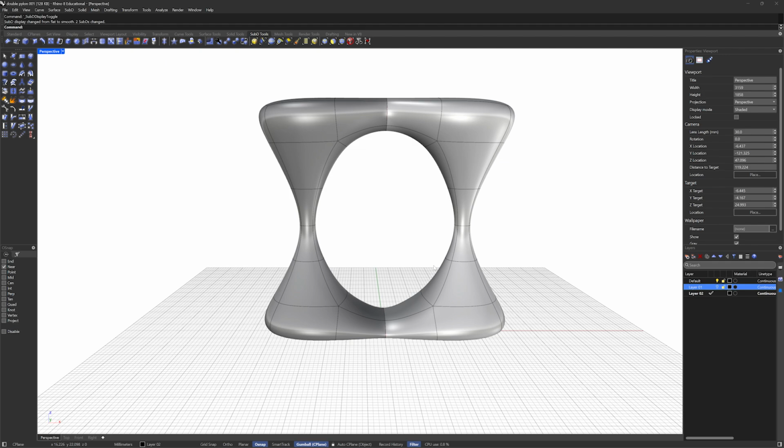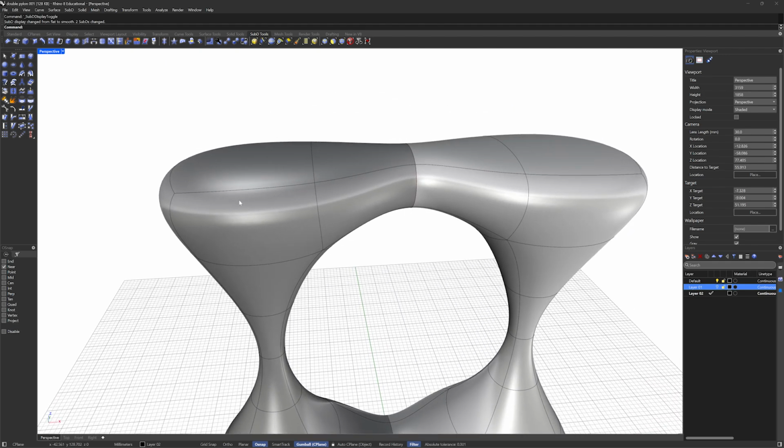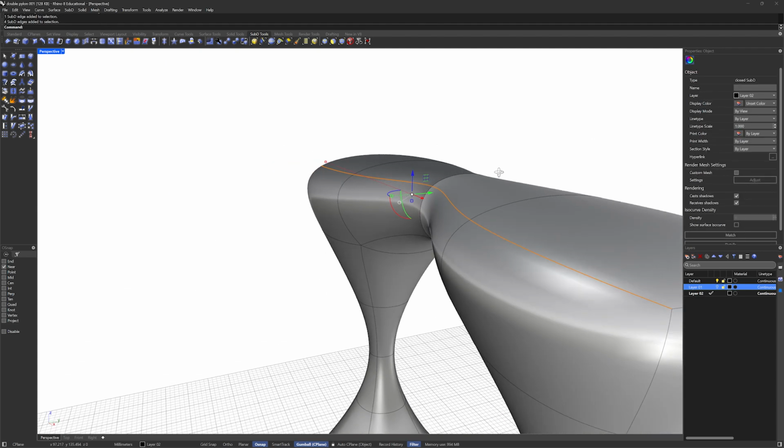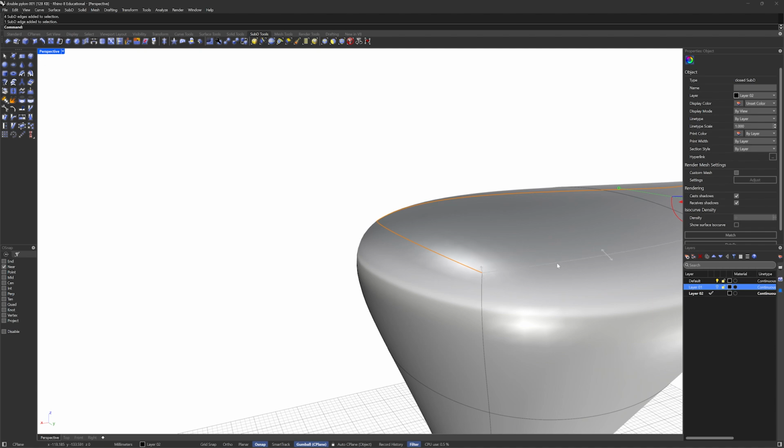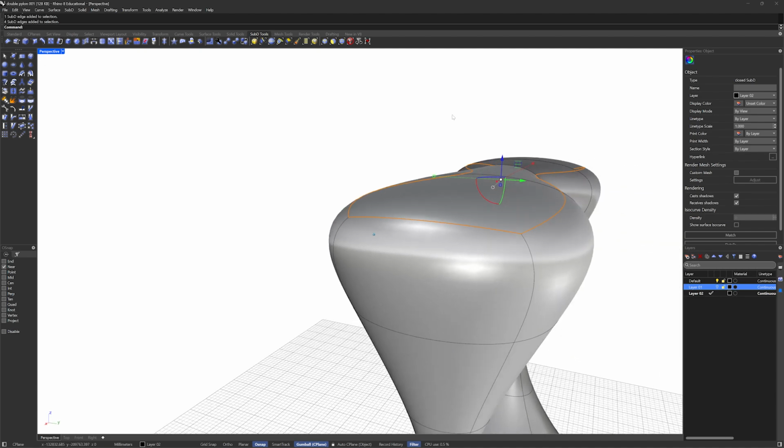However, it's a little bit confusing because the top is so continuously curved. And that's the basic nature of sub-Ds. So what I'd like to do, if you have an edge, doesn't matter how sharp, I still go ahead and crease it just so it's visually closer to the final. Let's do that right now. So I'm going to pick this edge, Control-Shift, double-click, goes all the way around. Get this guy here and that guy there. So this command is called the crease.